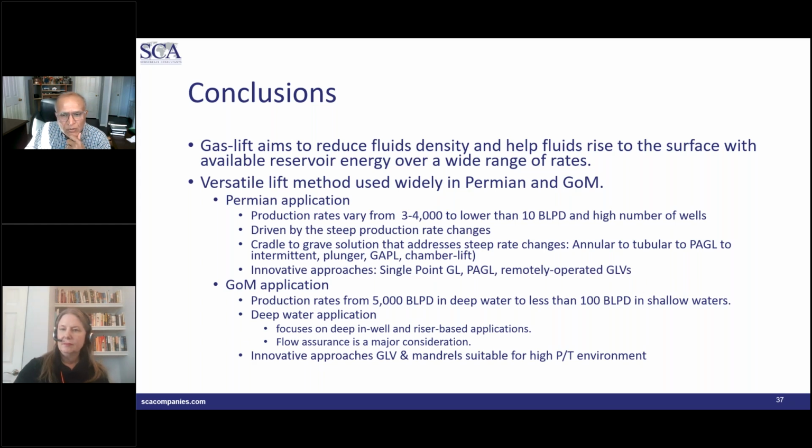Particularly, what we are trying to do is maybe change the cooling process when the gas comes out of the compressor, and try to not cool it down. So hotter injection gas can take care of some of that paraffin. So that is one challenge that I have seen.